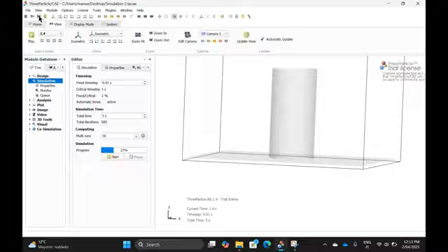I increase it to 0.01 and I start, and the thing suddenly starts moving at some point. Okay, that seems kind of critical, on the limit. Let's increase it even more. And boom, unstable. Going back, and again, so I find out which time step leads to an explosion of the system, right?